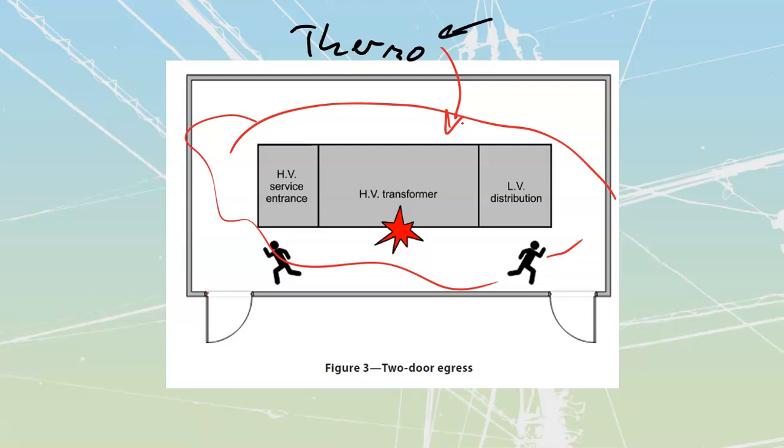We're also going to need to know if it's rated for copper or for aluminum. Not all lugs can be used with aluminum conductors, so it's going to have a CU/AL on them. And then we need to know what the temperature rating is going to be of these as well. If it's a 90-degree rating, it should have a 9 inside there. To give you an example, the CU9AL tells you that's copper, 90 degrees, aluminum as well.